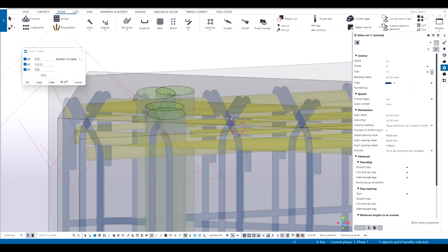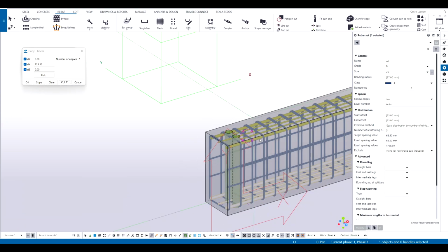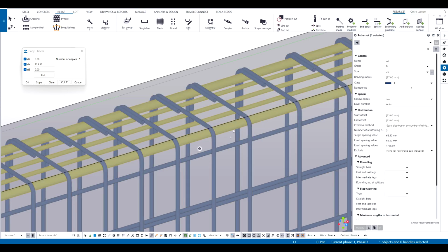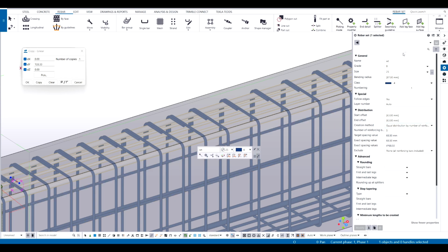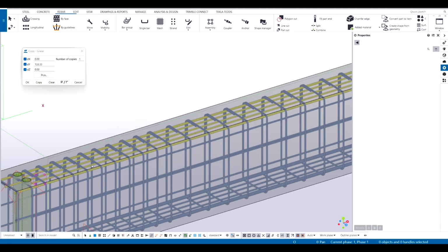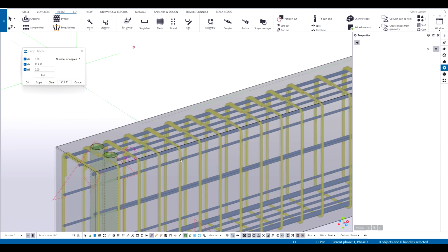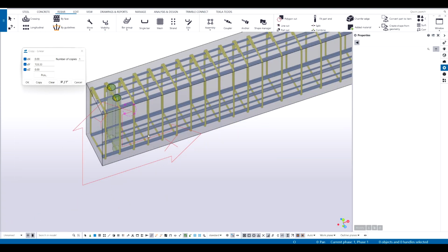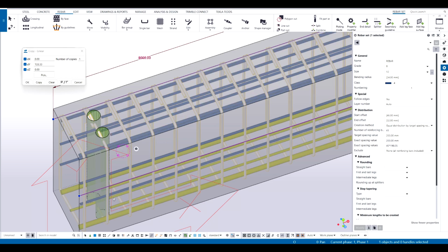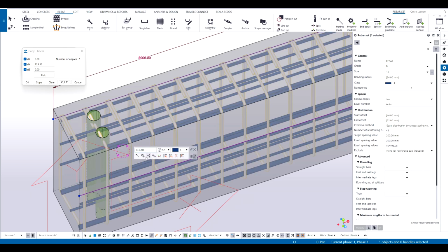So my beam is reinforced on the top and the bottom. I can basically just go here now. And I don't want 25s, I want maybe 16s. 16s as the main, but the middle ones, because I have a modifier on them, they'll adapt to what the modifier says, which is fine. I'm not too concerned with that. Now what I need to do is, you see this looks like it's clashing, so I'm gonna go here, see if it allows me to change their spacings.